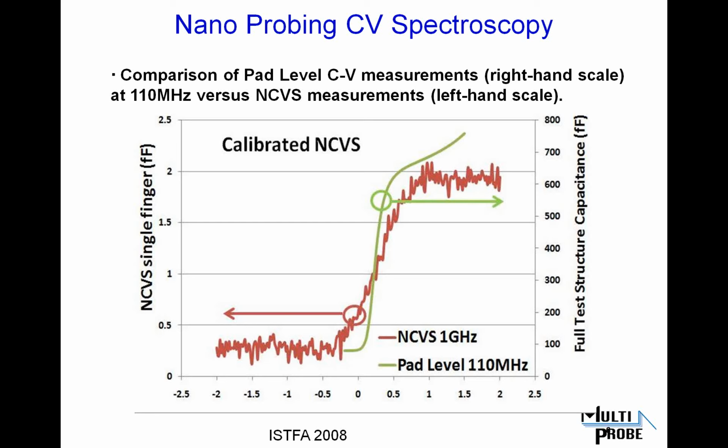So when the leakage happens, it kind of swamps the capacitance signal that is in that instrument, in the Agilent box, and so they find themselves having to calibrate that out, and it forms a real problem with being able to pick off exactly when the transition occurs. So it's not clear that the green curve is wholly without artifact. In fact, they go to great lengths in those types of parametric measurements, and in the end, mostly what they do is compare it to the previous lot.